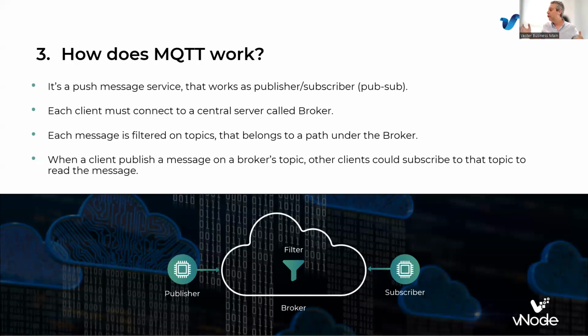So each client will be connected to this broker. Of course, this connection can be secure or not secure. If it is secure, it's going to be MQTT-S. It's going to need an exchange of certificates, and then all the clients are going to be connected to this broker.